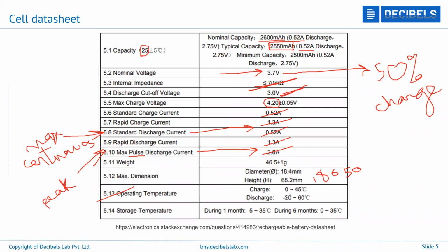So these are then the operational temperature limits. During charging and discharging, it has to be ensured that these two values are always kept, so that the cell does not start to get damaged by functioning outside these limits. And then finally we come to storage temperature. Storage is basically an isolated condition where the cell is just kept in a particular storage device or facility, and the temperature that we set inside is dependent on the duration of storage.